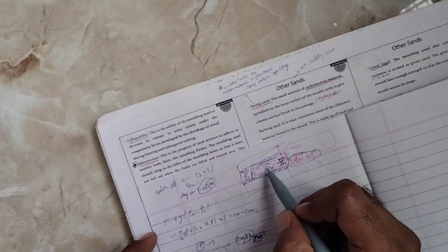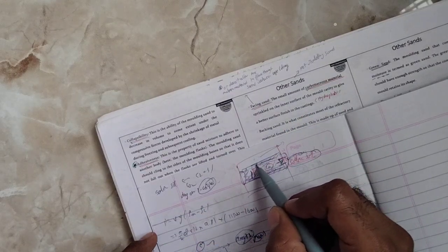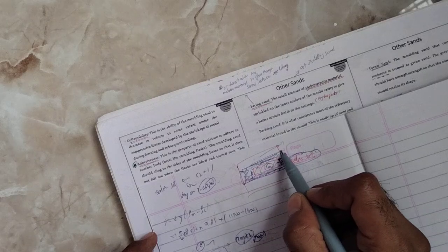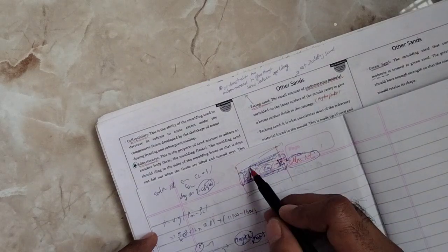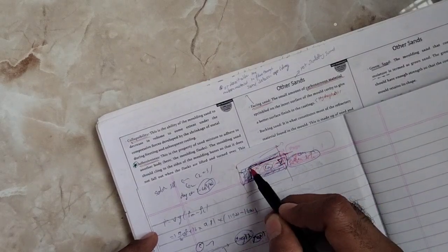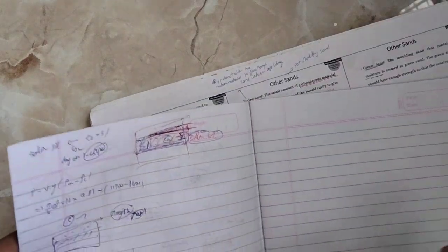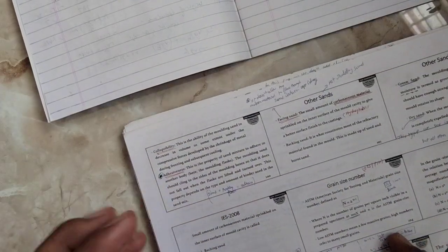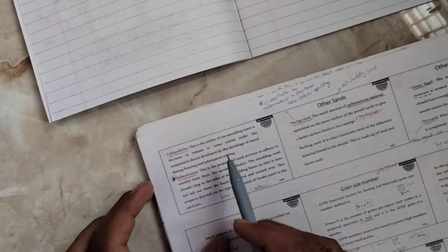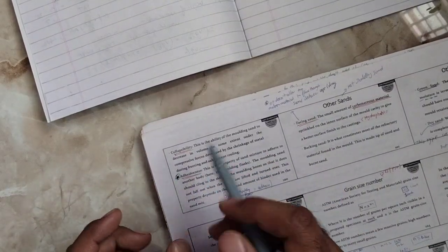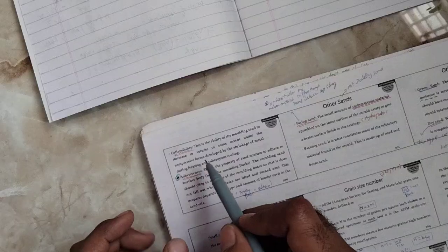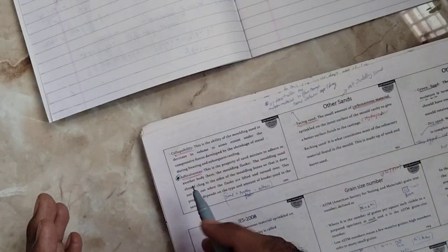If it doesn't shrink, you can see this entire thing will collapse and will just form like this. Instead of being like here, you can see in this area it will tilt to this area, a little bit of increase, meaning the outside volume will increase. Okay, so the core should have good collapsibility, and each and every molding sand also should have collapsibility, it should decrease a little in volume to a certain extent under the compressive force of the shrinkage of metal. Okay, so next one is adhesiveness.